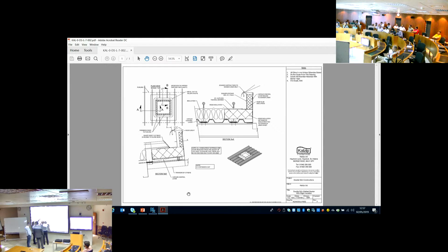So this one, how will it move? This piece moves 5 centimeters. Again, this piece, which is cut, this portion. But this sheet has the same effective length, the same fixed point, one fixed point in the same place all the way. And this is where you control the movement. So over 10 meters, it moves 10 millimeters. It's longer at the far end.